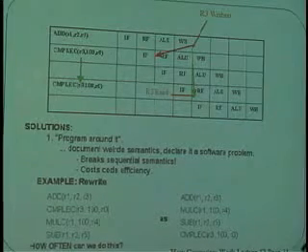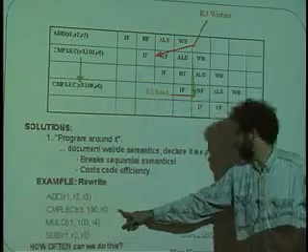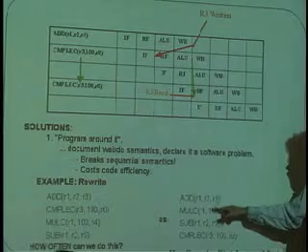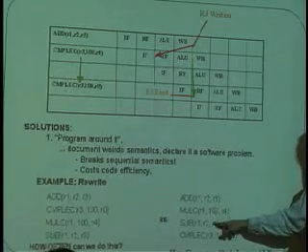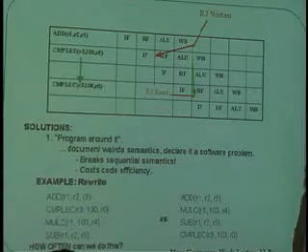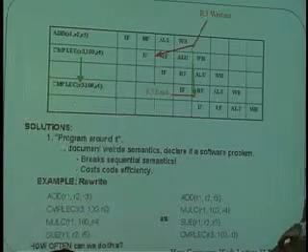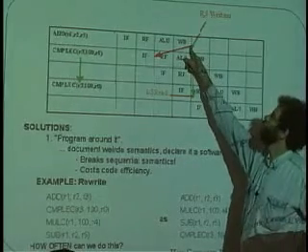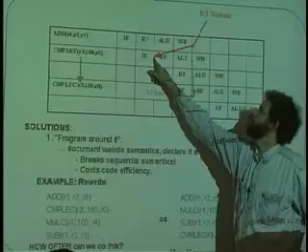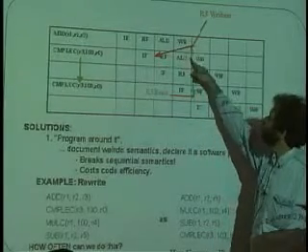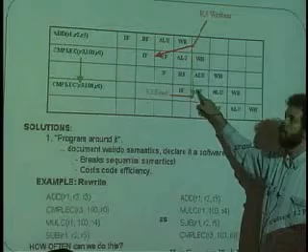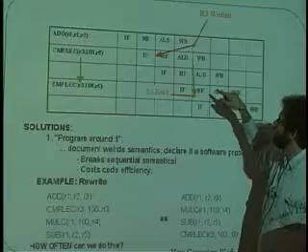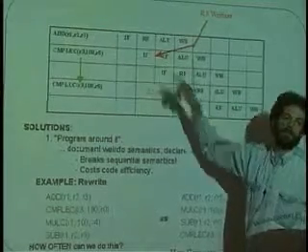So I would move the compare less than from over here to later on down here, so that by the time I want R3, several clock cycles have passed, several other instructions have been sent down the pipe, and you can actually figure out from the machine how long you need to time delay it, so that instead of this line over here going from a write of R3, which occurs later in time from when we need it, we have the write of R3 happening just in time before we read it in this stage over here, if the compare is in this line as opposed to this one here. We read the register file here instead of back here in time.